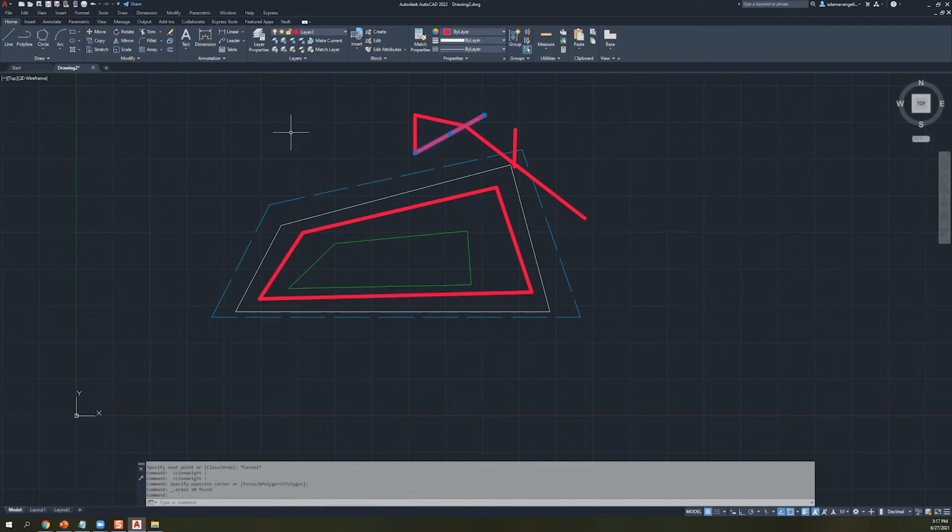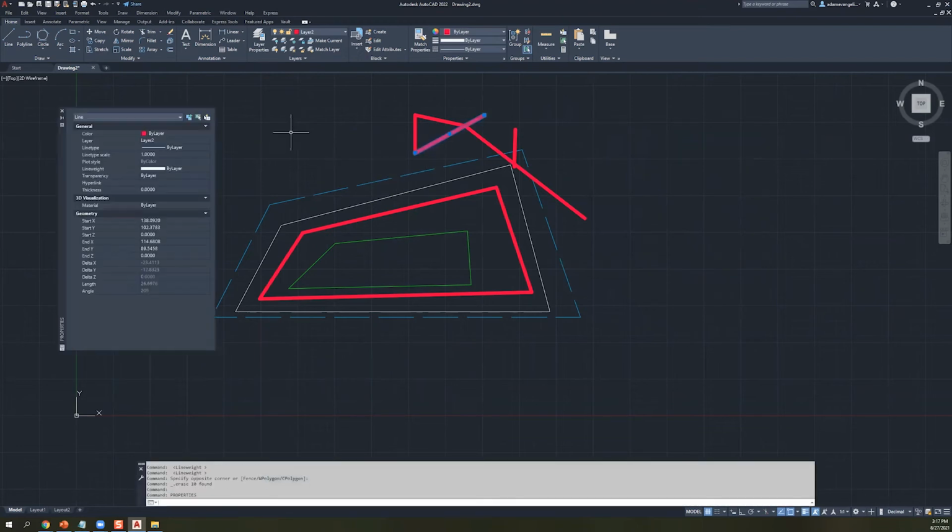Notice when I start clicking on objects as well, and I pull up properties again, it'll start giving you more information about this specific object. And the information about this object is unique in that it is dynamically driven by a layer option. Like color, for example: the color of this object that I have selected is set by layer. What is the color from the layer property saying? It's saying this weird magenta color. It's a red magenta color, right?